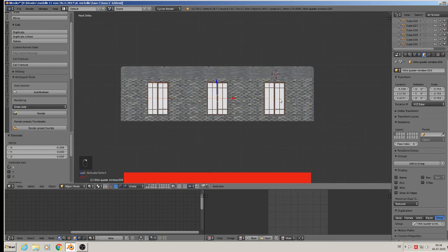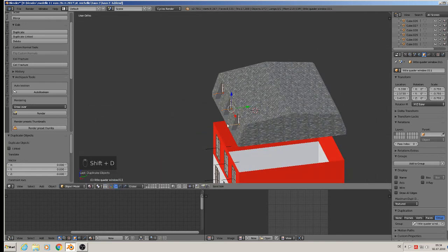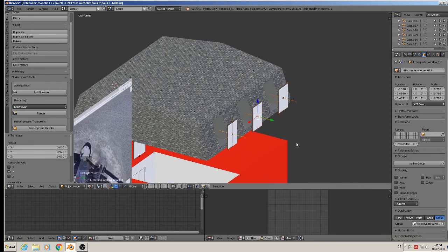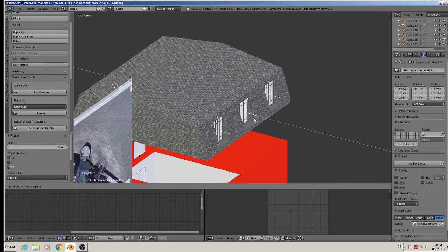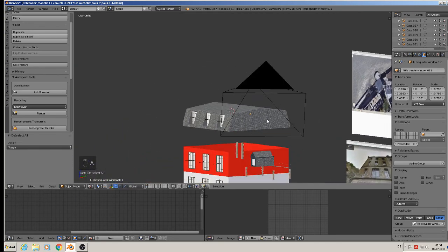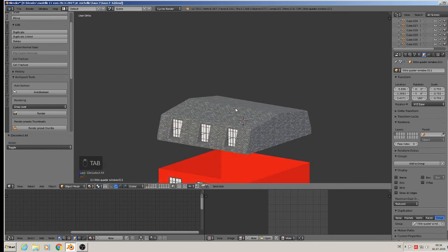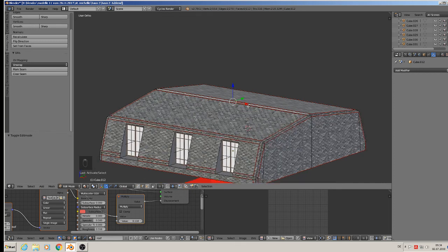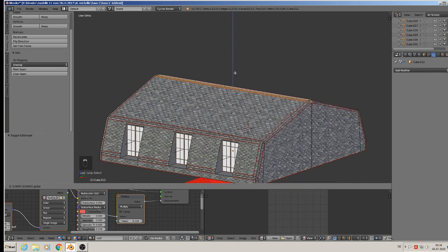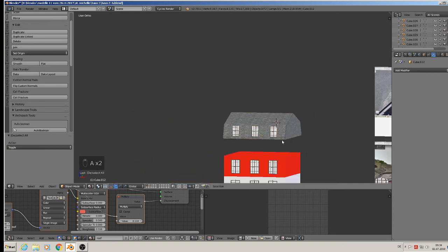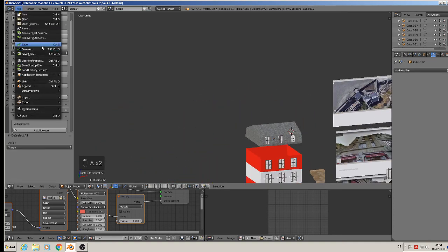And we can take these 3 guys and Shift D, bring it there. Simply have to rotate that, rotate set 180, so that it turns around and bring them in. So roof is done. I think that here can be a little bit higher. So you simply take that and move that a little up, so that looks better. Good. File, save.